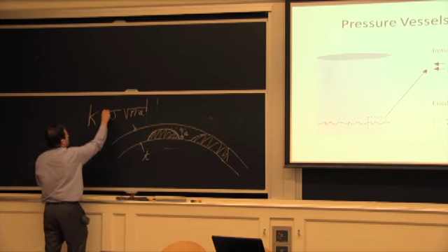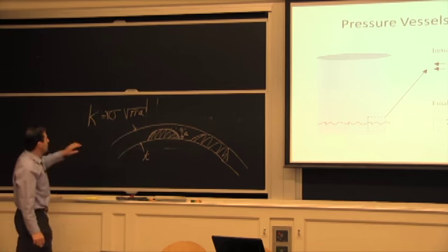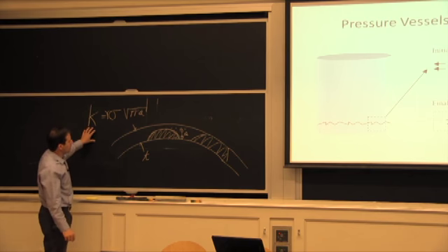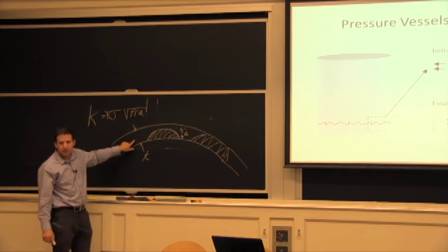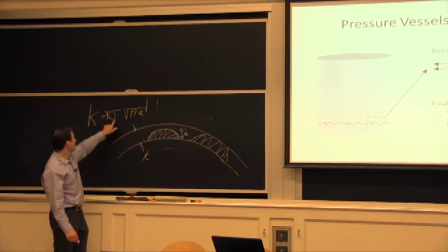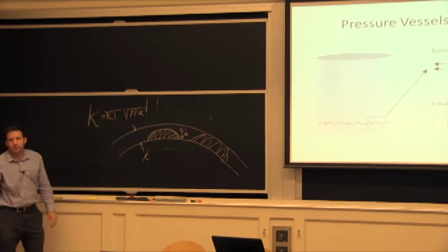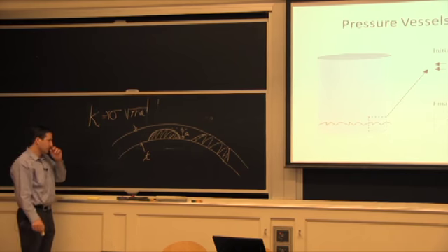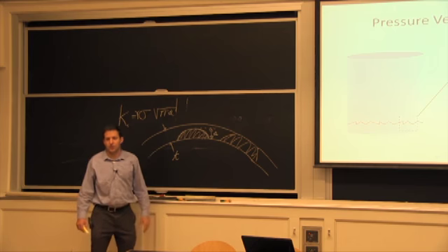And then we can add a little fudge factor here. So the idea is, for a given application, you want a to reach t, giving you a level of stress, and all of this be inferior to the toughness of the material. And then you can say, oh, I want it to be a certain size.